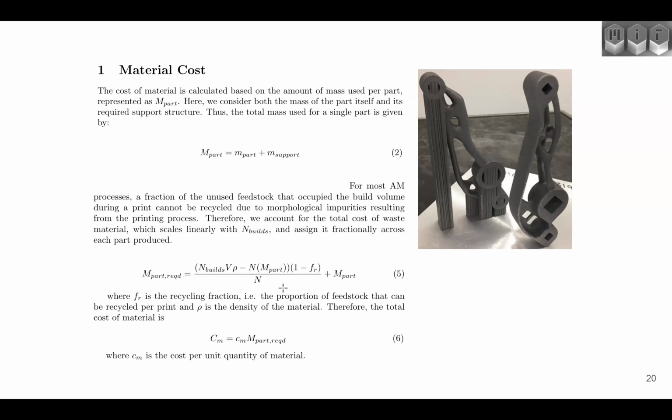And that damage means that those powder particles can't be reused. And this is not a trivial number of particles. This is a single digit percent of your build. And when the material can cost $200 per kilogram, a single digit percent can actually add up. So in this case, we also want to account for material losses in the process.